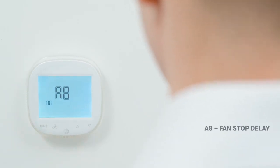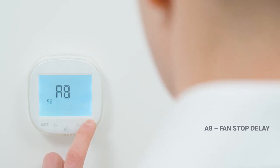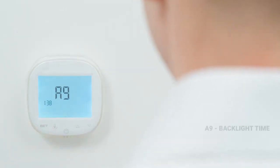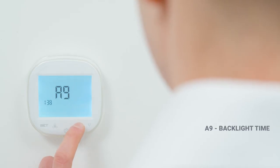Function A8: setting the fan stopping delay time from 30 to 200 seconds. Function A9: this is the backlight time of the controller display. We have the possibility to select values from 5 to 600 seconds.